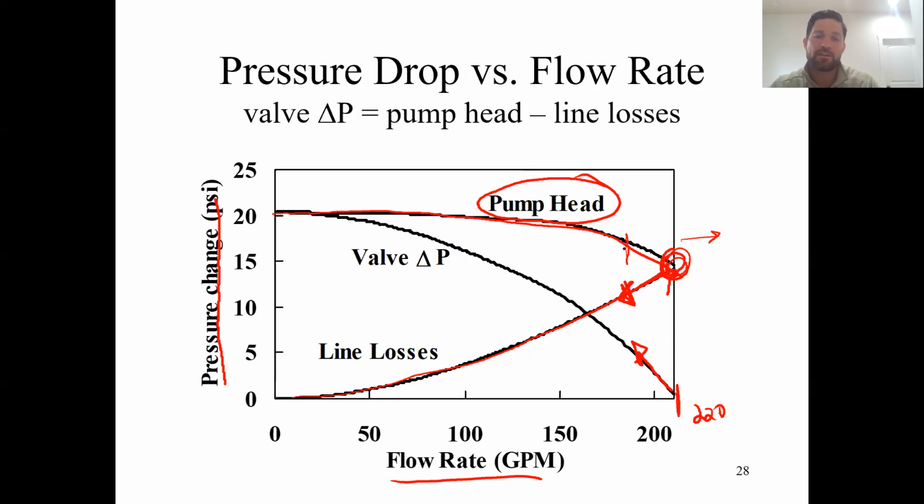And then because we have gone to a slower flow rate, now the pump is giving us a higher pressure. So this point right here is essentially the maximum point that we can achieve based on the process as it is designed. If you try to go beyond this point, it's not like something magical happens. It's just that you can't get any more than that.